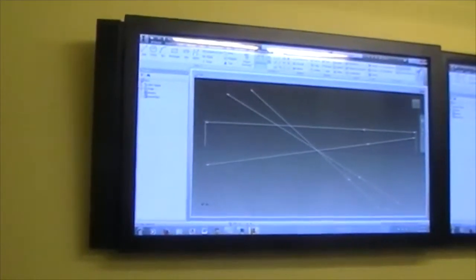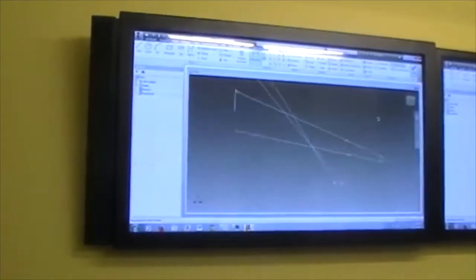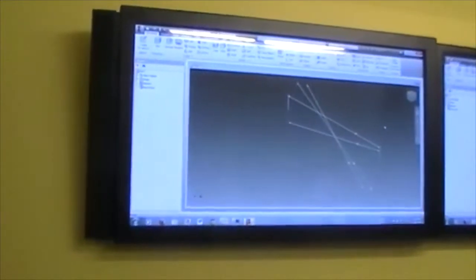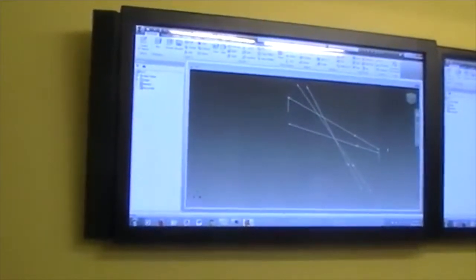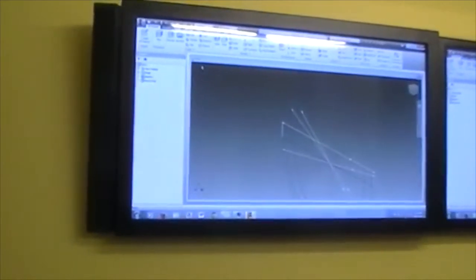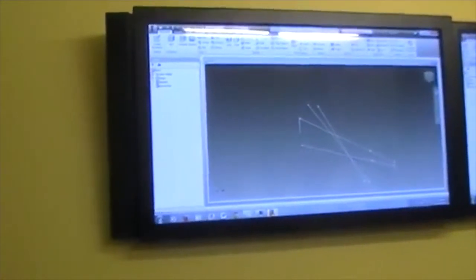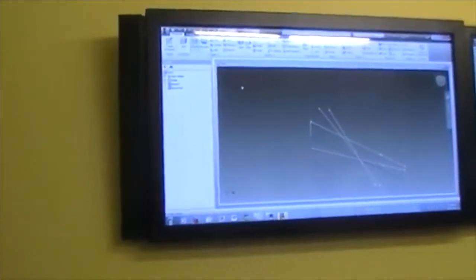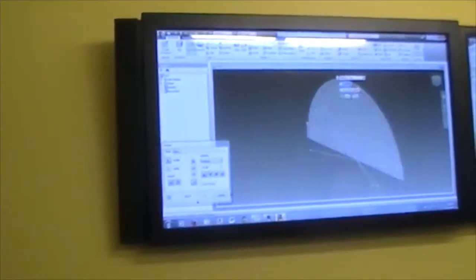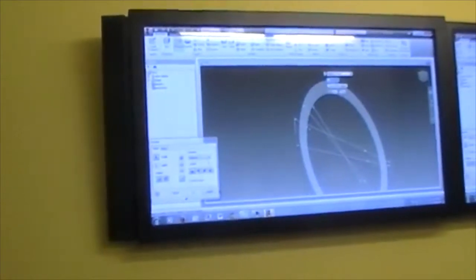So now we come here, the second most important button on the right, which is Finish Sketch. Click that, and we've got a 3D sketch here that we can now do something with. Okay, so I mentioned extruding, that's pushing or pulling. That's what we're going to do. So I click Extrude, and then I can select a specific profile that I want extruded.